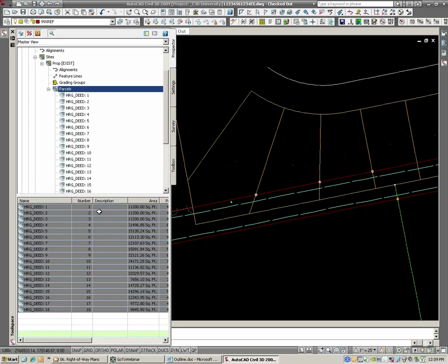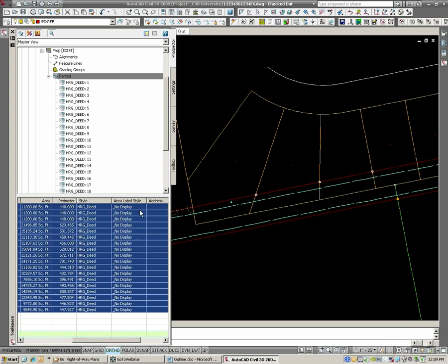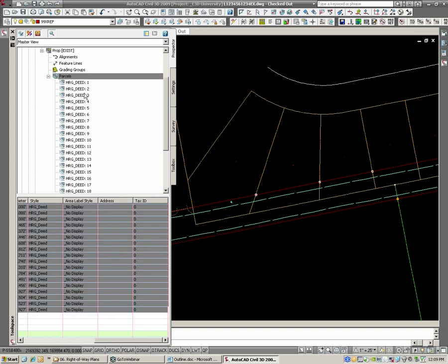But first I want to look at these parcels and look at the numbering. You can see they have parcel numbers assigned. And in our road right-of-way plans, we usually have a lot number, a property identification number, for each existing conditions parcel that's affected or not affected by the property in the area. So we want to pull that information out of our numbering here. First I need to get an idea, is that numbered correctly? To add labels to all these parcels in the existing conditions file, all I need to do is click on the parcels category here.